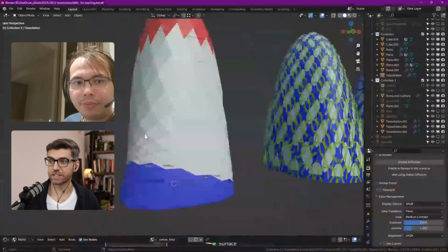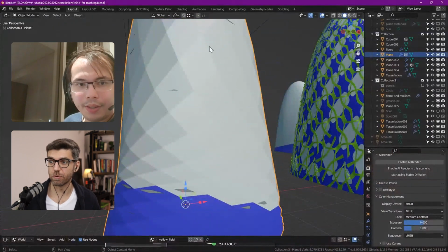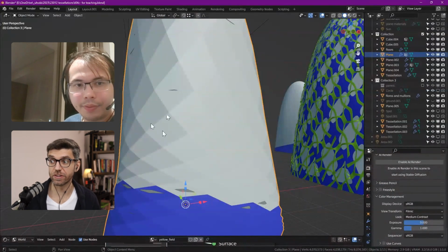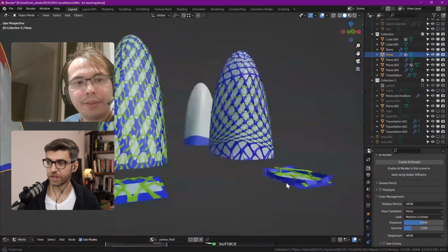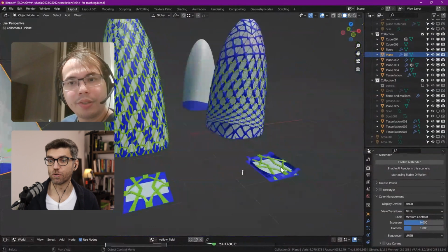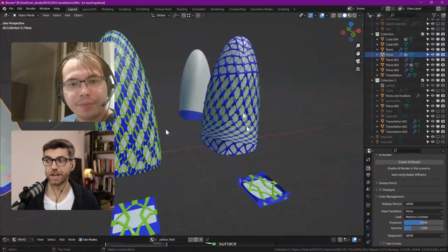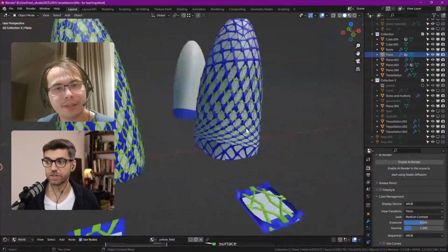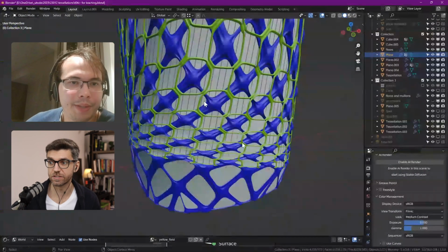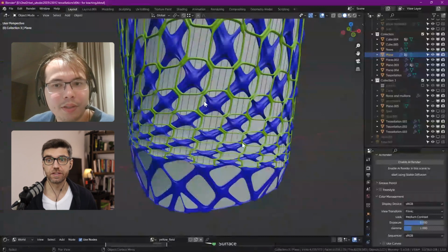This one is tessellated. It starts out with these, and on each one of these faces we get one of these panels. Because this is very early concept, if this were to get built or advanced more, there would be a process of rationalization, because right now each one of these panels is unique, a different size. Ideally we would want to narrow this down to three sizes.